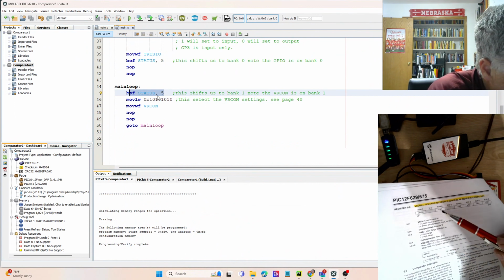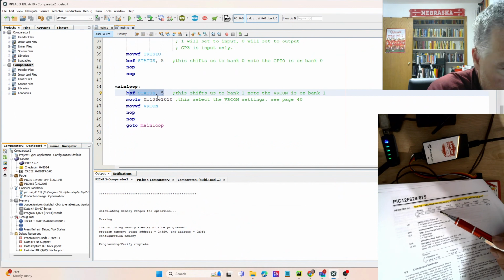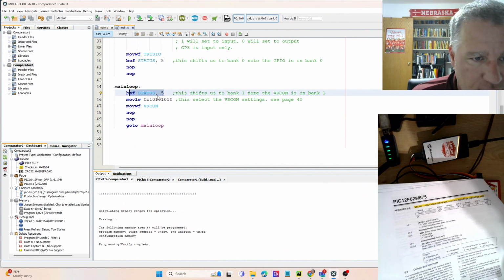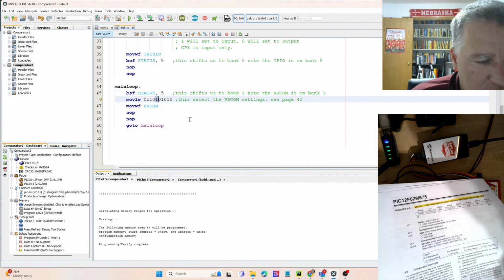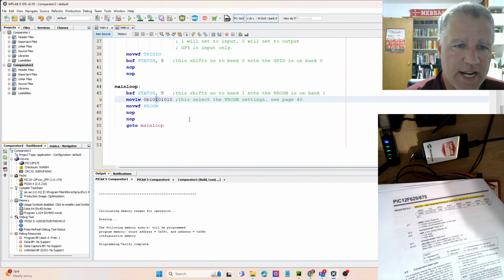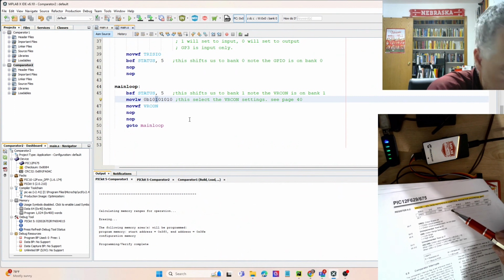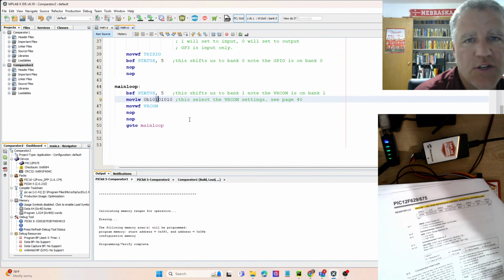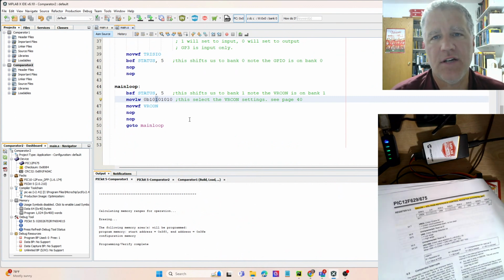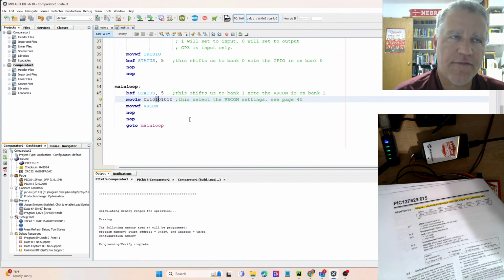So the VRR here is going to be set to 1. So that's this one right here. That says we're using the low range. Then the bit over from that carries no meaning. And then for the remaining 4 bits, we type in a binary number that will be a fraction of 24.